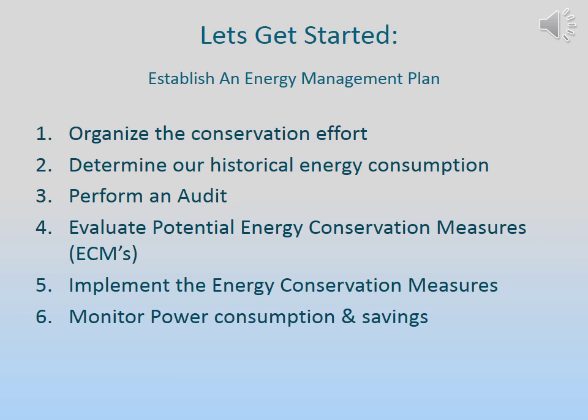We would want to track the dissolved oxygen level, because if lowering the dissolved oxygen is one of the changes we decide to make, we would need to track what impact it had on the process over a period of time. We know we can change the dissolved oxygen, but how well do we control it over a period of time?